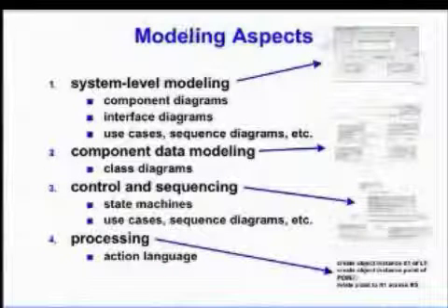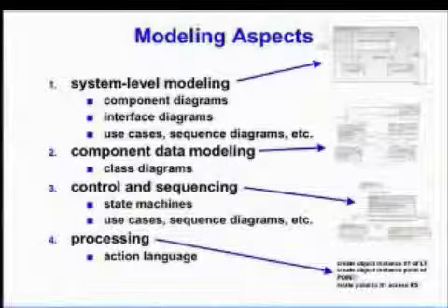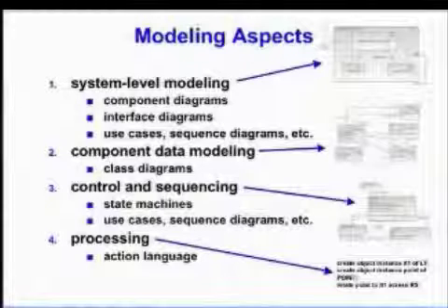The framework that we'll use in the demonstration here is that we'll basically go through all of the steps of modeling and development to ultimately get us to a running target. The modeling aspects include system level modeling, where we will break the system down into its various components. We use component diagrams and interface diagrams for this work. We can also augment those with use cases, sequence charts, and other documentation-oriented diagrams inside BridgePoint.